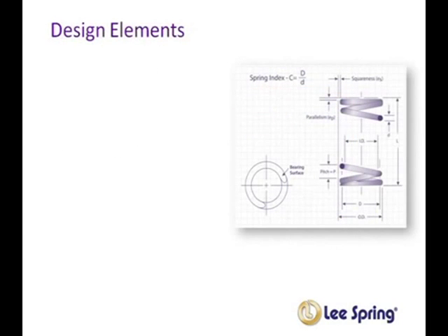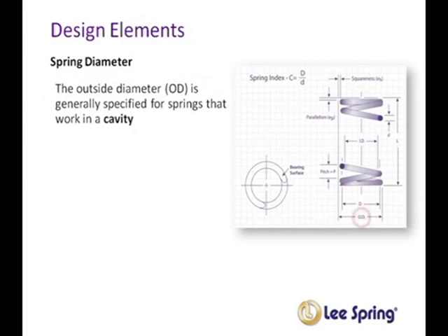Now let's take a look at the physical dimensions of the spring, specifically spring diameter. Spring diameter is often referenced in a couple of different ways. One method is the outside diameter, or OD. This dimension is important when the spring is used within a cavity.